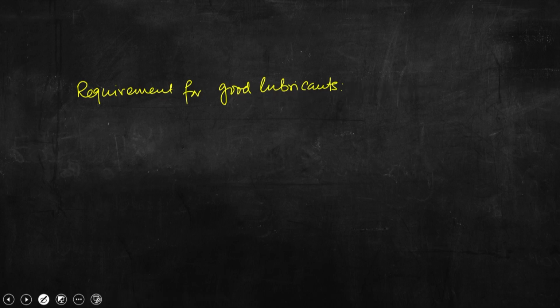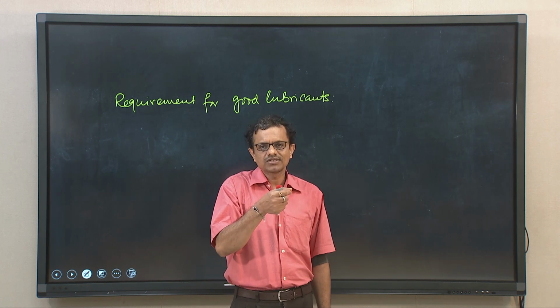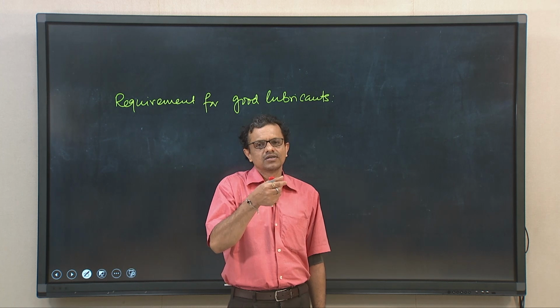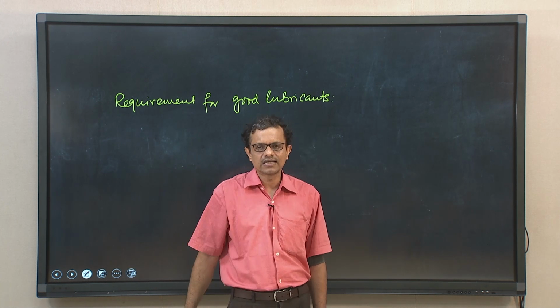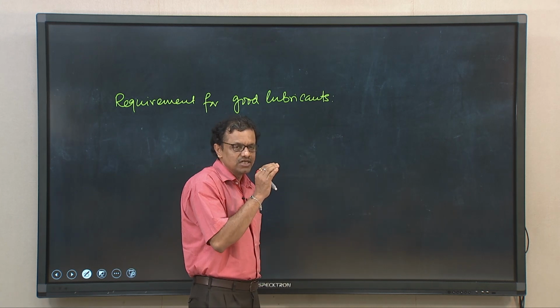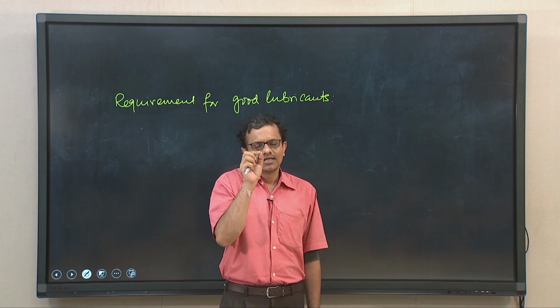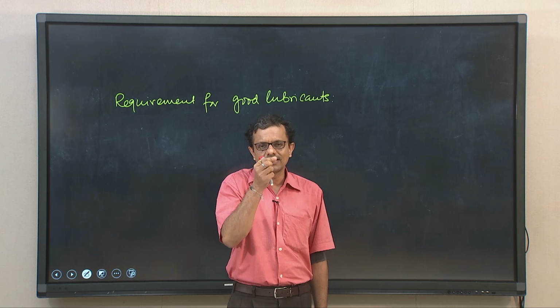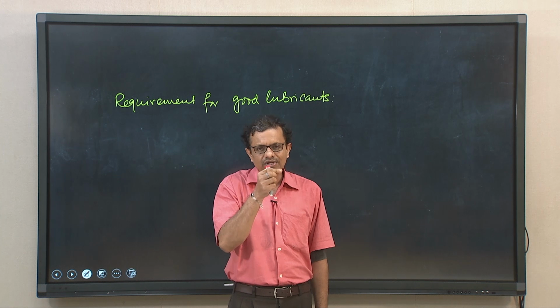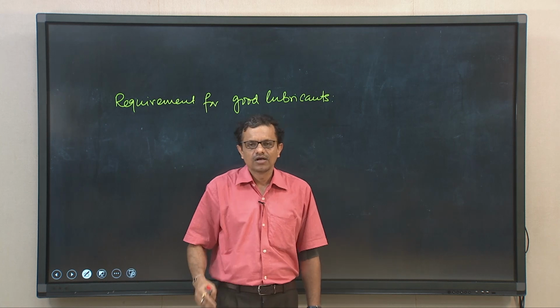So, this is very important to know for any designer of engine. You can see that lubricant will be supplied so as to minimize frictional losses and to prevent mechanical failure through the formation of wear and tear. As I told you, lubricant will be supplied to the passage in between the piston outer surface and cylinder inner wall, and that lubricant will experience huge shear stress, because the piston will be having continuous movement.